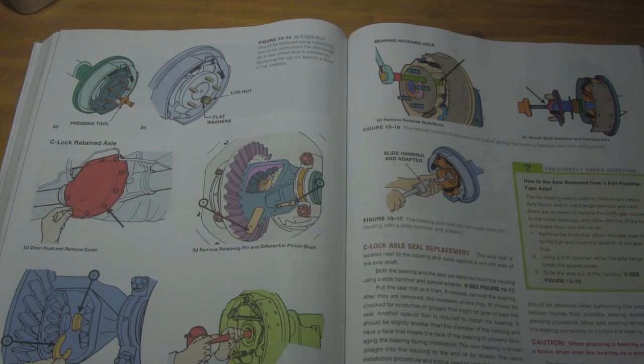So when you're tearing down the axle, what I'm talking about here is checking things like rotational force on a pinion gear. We can actually check the preload of the pinion bearings. You can see if they're worn out. You could check for backlash. You can have an inspection on seals and seal shafts. So is the surface area that the new seal is going to ride on adequate, or are we going to have to replace a component before we put it back together? Be mindful of the teardown procedure. You want to be looking for any problems as you're going. You don't want to just tear down the axle and have a big pile of parts.